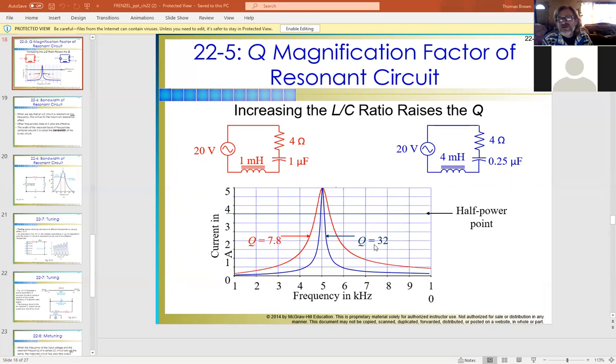And notice the Q factor involved. So this one on this side would be the type of circuit he's referring to, having a high Q factor. It's much more in balance with itself, as far as our X of L equaling our X of C, these would be a much tighter ratio than these.